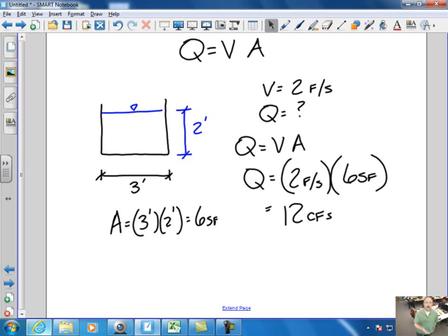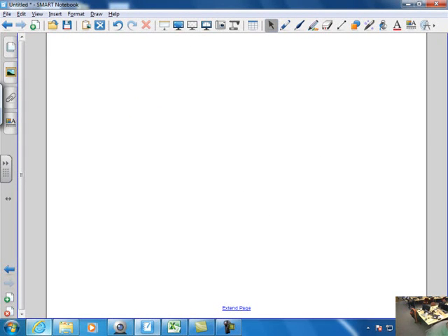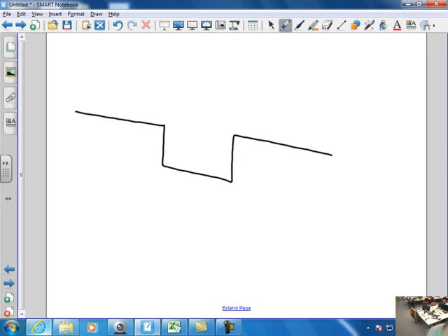And this is how they go about doing measuring stations across dams or waterways. They'll have a section, and they'll actually have a notch in it, a weir, at which they're going to measure the depth of water coming across this. So they'll measure the depth.